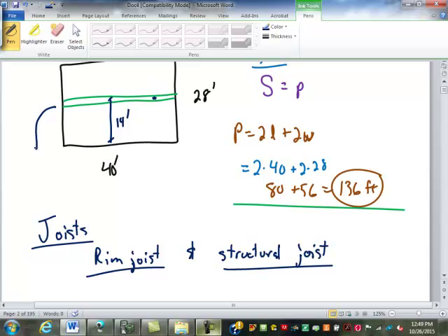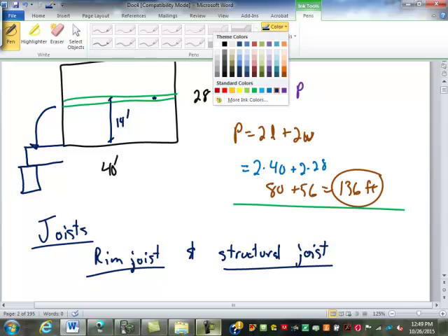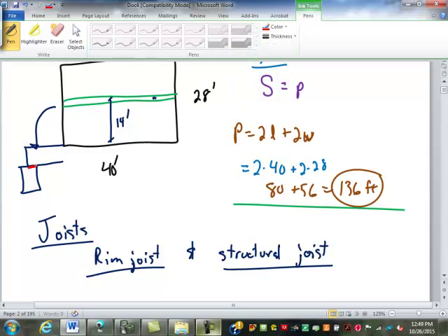If I'm looking at this beam here in the center, when my joist sits on it, this point of contact between the joist and the beam, that is the bearing area. We're going to assume that the beam is wide enough that the joist can sit on it and cause bearing. And we do get an extra 1.5 inches anyway because your rim joist is 1.5 inches or whatever, because your rim joist sits out here and pushes the joist in that 1.5 inches or whatever it is anyway.